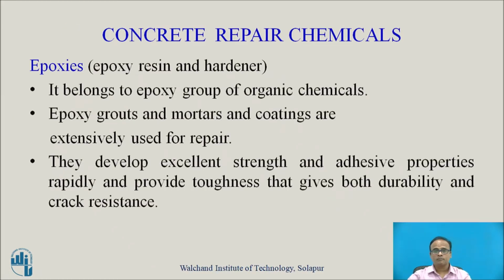Epoxies mean a combination of both resin and hardener. It belongs to the epoxy group of organic chemicals. Epoxy grouts and mortars and coatings are extensively used for repair. The epoxies develop excellent strength and adhesive properties very rapidly and provide toughness that gives both durability and crack resistance.